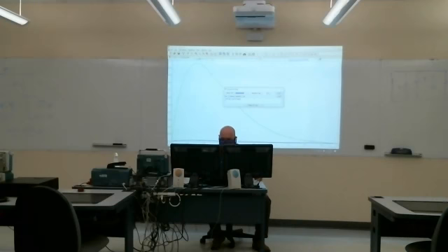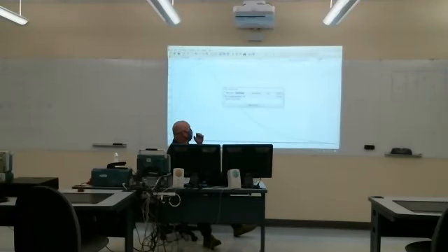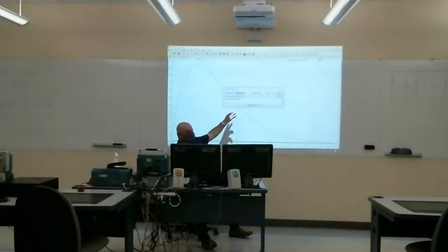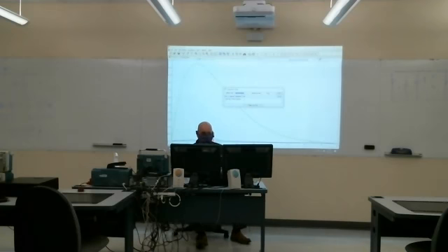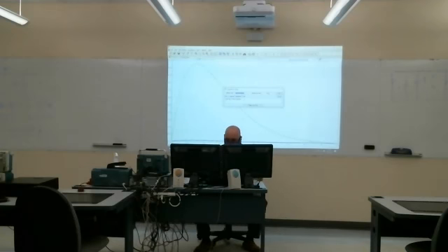But part of the reason, I don't know if this is the only thing that's wrong with it, but part of the reason is in LTspice, unlike almost every other software package in the world, the argument to the sine here has to be in degrees, whereas here it's in radians. So I have to convert this to degrees to make LTspice happy. So I have to multiply by 180 and divide by pi. And then there they overlap. So I'm pretty confident that we actually got the right solution there.